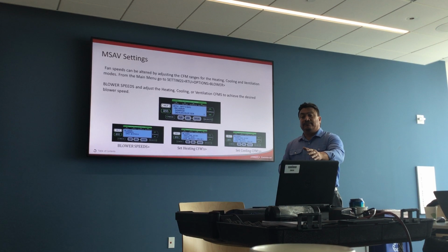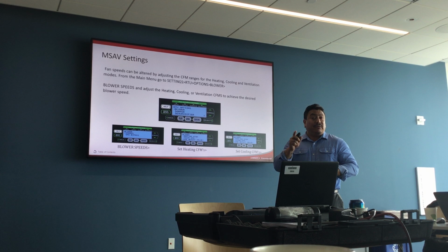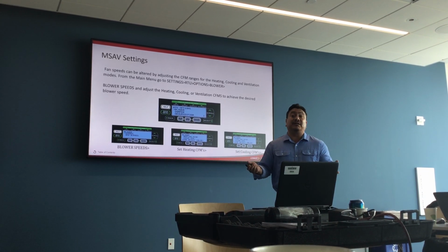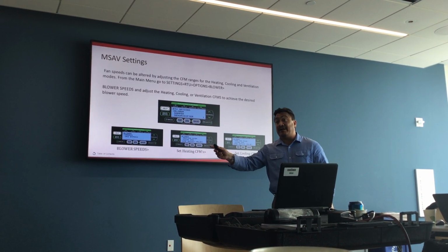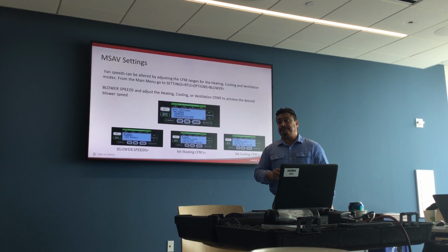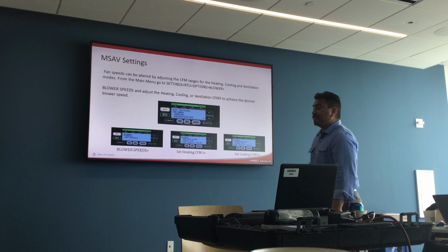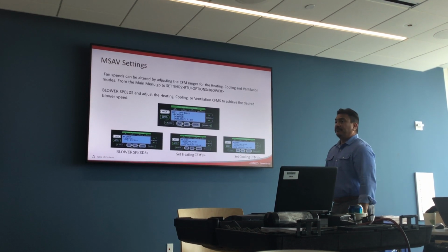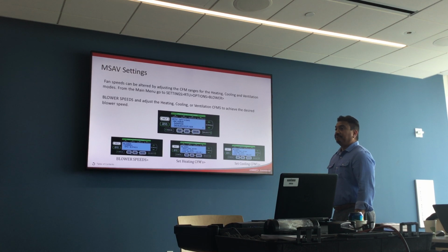I'm sure the other gentleman who will come on at 2:30 may clarify this, but he also may have the ability through your front end to put the unit in occupied, because it's basically a 24 volt signal. So your front end may be responsible for providing that signal to the unit. Yeah. Remember the first time I brought up, I was trying to use the Prodigy board to do my testing for the HVAC PMs, but I could never get that. I got everything else to work but the blower. Right. So maybe I still need to add that 24 volt, and it isn't going to affect anything else if there's another wire hooked into the occupancy.